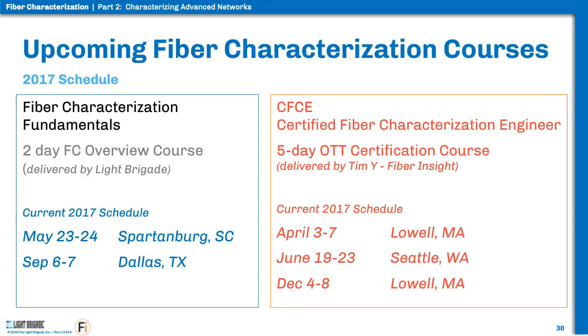You're saying those three? OLTS, OTDR, and ORL. I would say they're equally important. If you think about an optical network, your insertion loss measurement is your baseline. You've got to know whether you're going to be within the link loss budget.